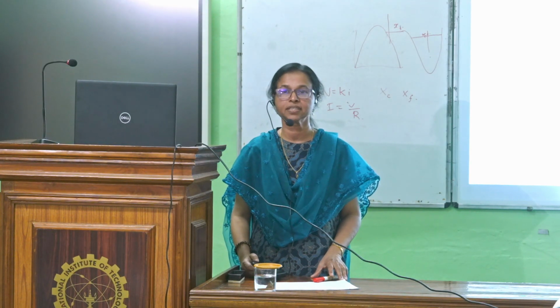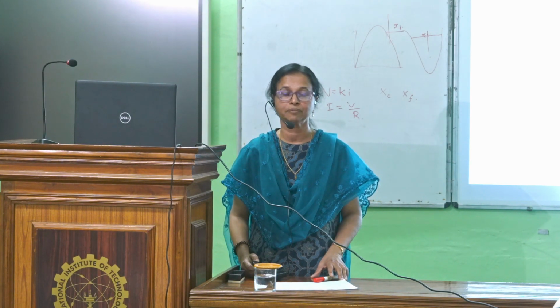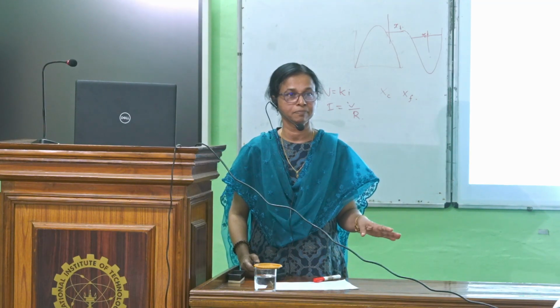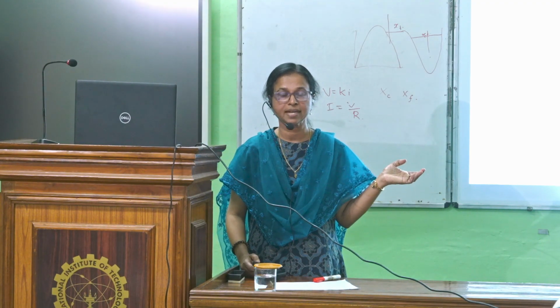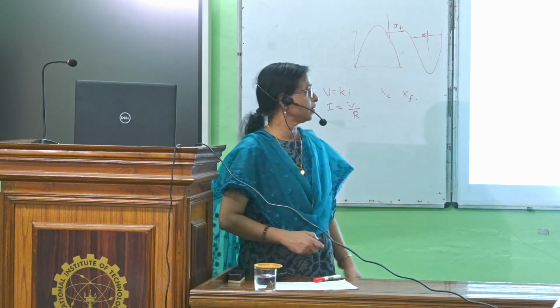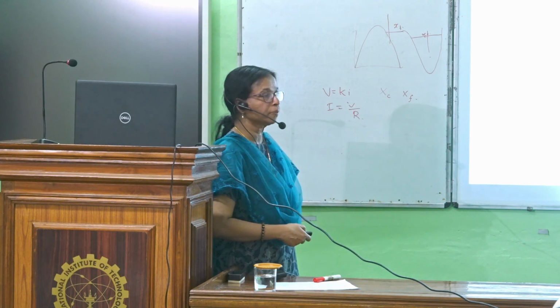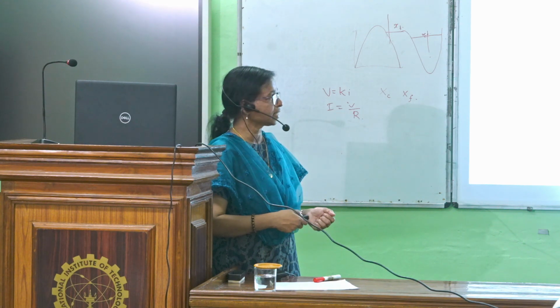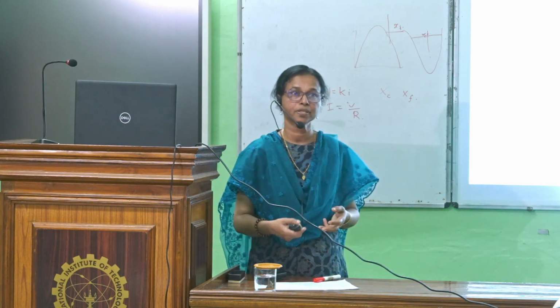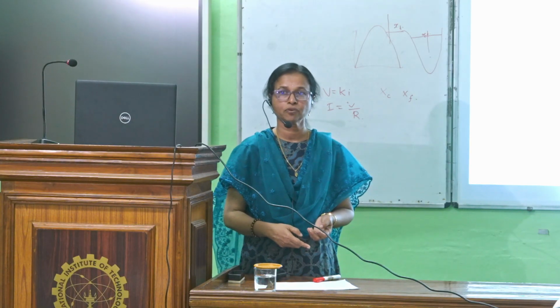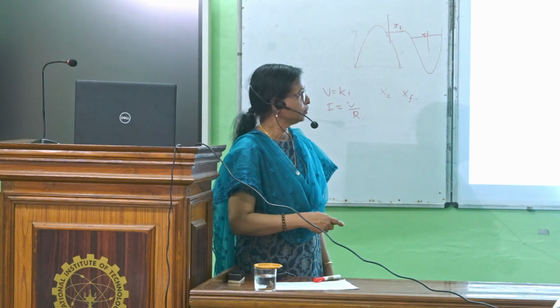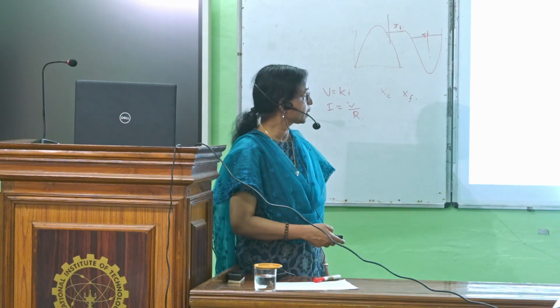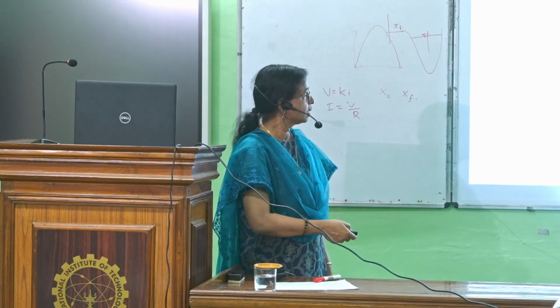So what are the different methods of gradually varied flow profile computation? Direct step, standard step, etc. Here HEC-RAS actually uses the standard step method, where you have to assume a particular water depth, whether at the downstream or at the upstream, depending on the flow profile.